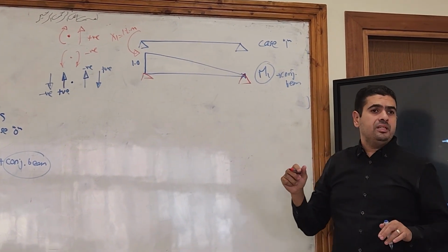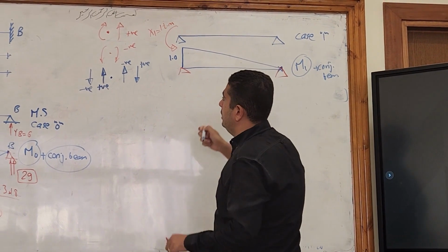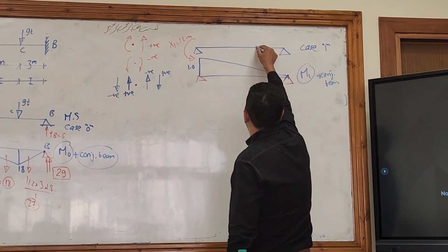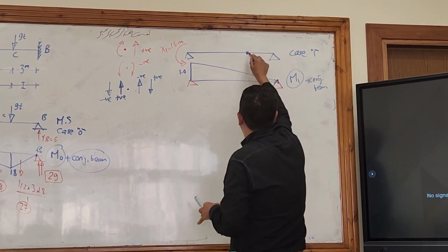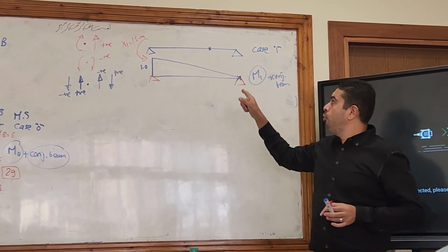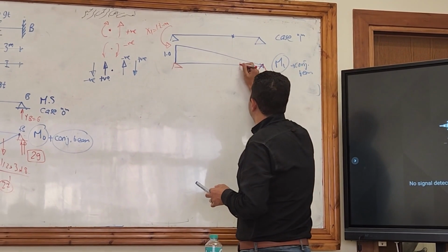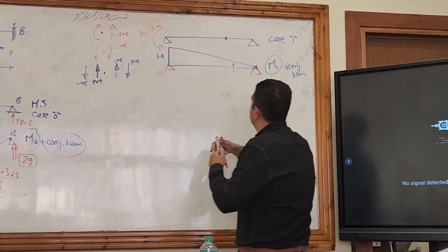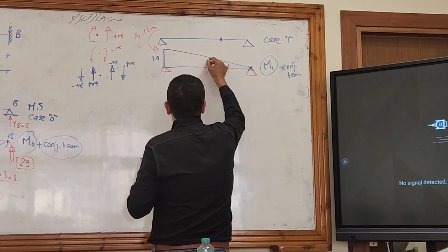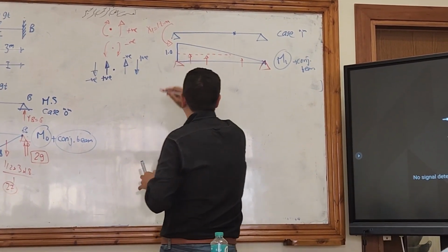You need splitting? Yes, I need splitting because I have a difference in inertia here. So I have to split this triangle. I can't make it 1 triangle. So I have to split it, this triangle, and then trapezium on the left, which will be a rectangle and a triangle.